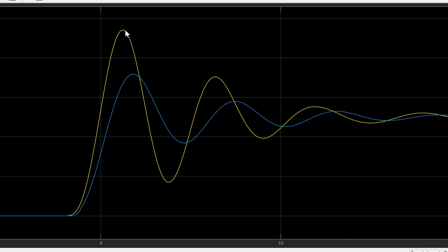Let me have a look at this. Probably the frequencies are the same. I'm just going to check the frequencies. You can measure it from peak to peak. So I'm going to do a peak to peak on this, which is that much. On this one, the peak to peak. Yeah, so if you look at the peak to peak on these, that's the time from there to there. It's the same as the time from there to there. So the frequencies are in fact the same.